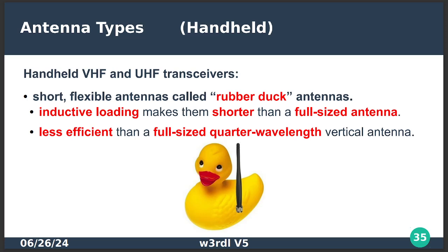You do have to be cautious because that connector on the top of the radio will eventually give way to the constant pressure from having a coax attached to it. So you use like a 2 or 3 foot piece of RG316 on there, so it lessens the tension on the connector, and then attach your coax for an outdoor antenna up higher, much better SWR, so you get more out of your 5 watts that way. You just lose the portability.